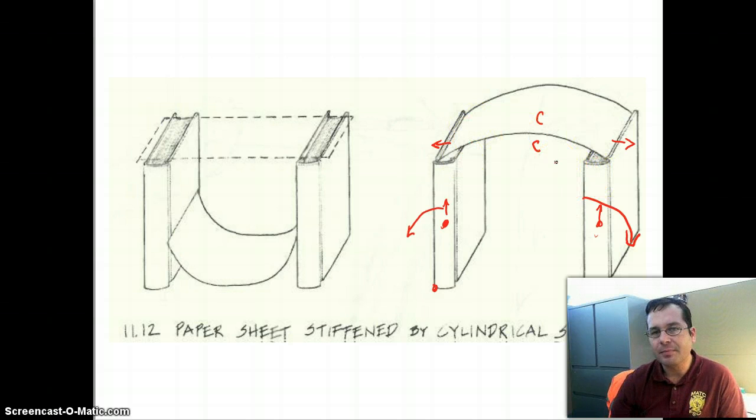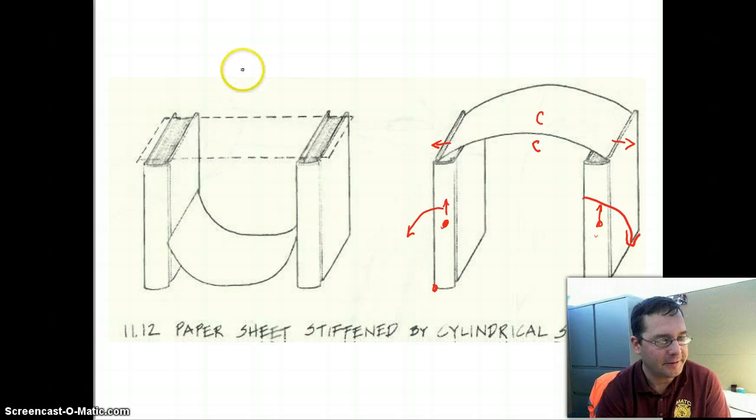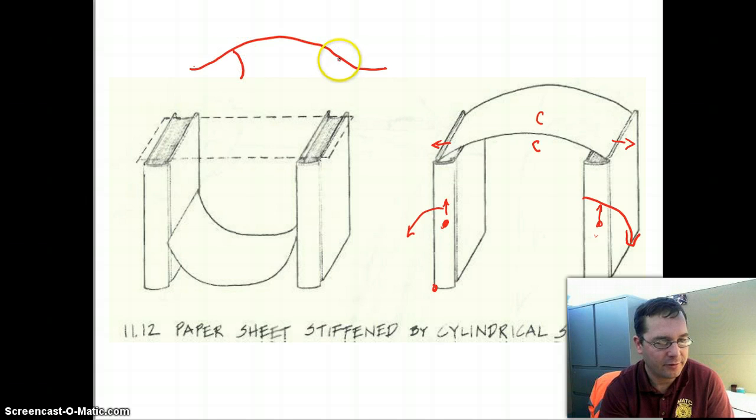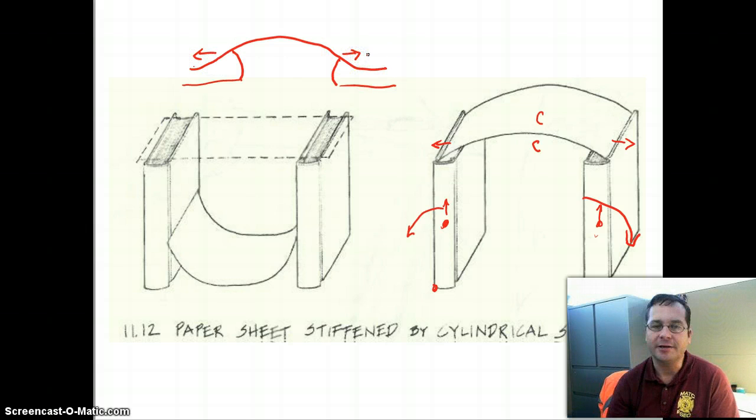Now, in actual construction, you'll see this done, and some examples are like at Tenney Park, close to the college here. There is an arched bridge that crosses the lagoon, and if you were to look at it, on the ends of the arched bridge, there are earthen embankments. And the purpose of these earthen embankments is just simply to provide something heavy to resist the outward thrust produced by the arch. You'll read about other things in the textbook, such as flying buttresses. That's another approach used in kind of classical construction to try and resist this outward thrust of the arch.